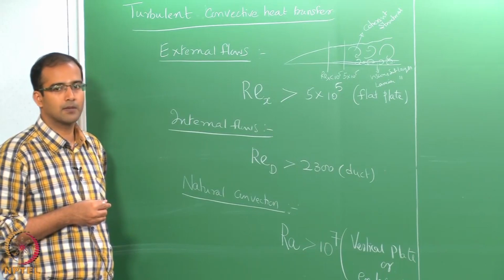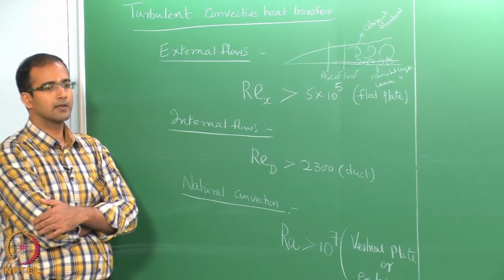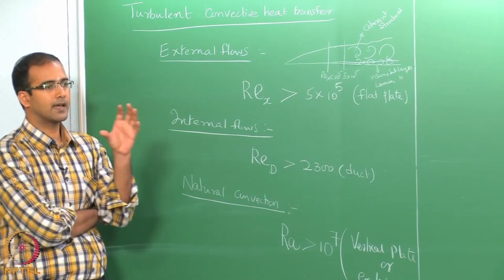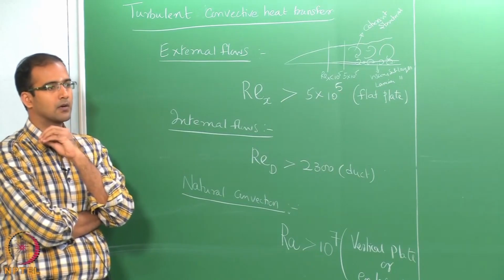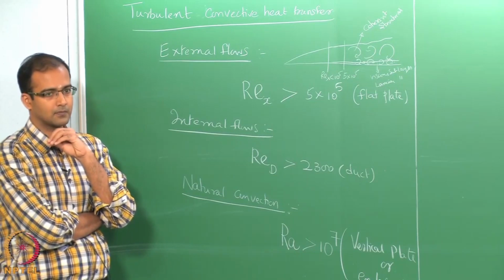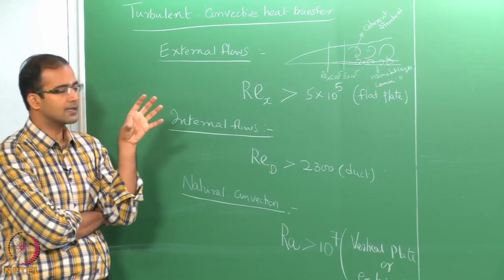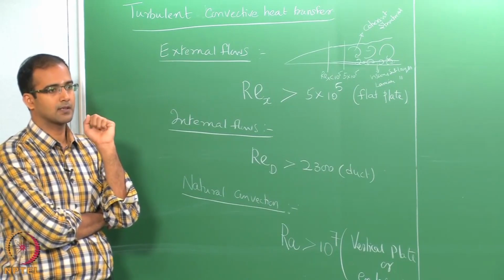In the case of a typical boundary layer profile, the effect of the wall is to damp the large scales, and the large scales cascade to smaller and smaller eddies, and finally it becomes laminar close to the wall, okay. Only in this laminar region do you have the significant effect of molecular viscosity.